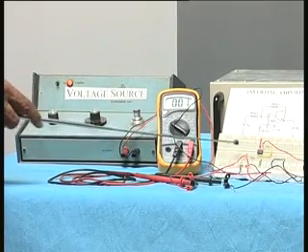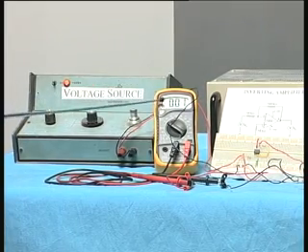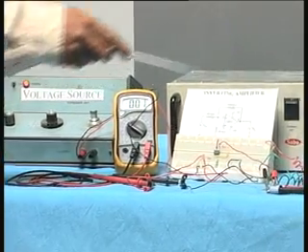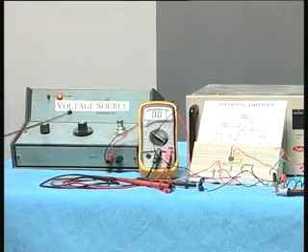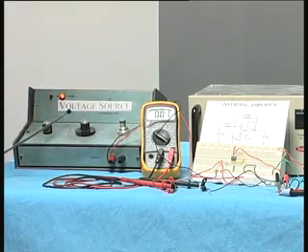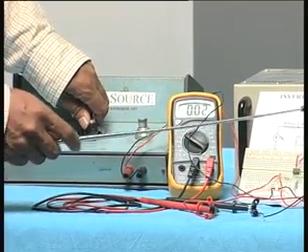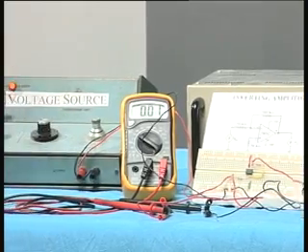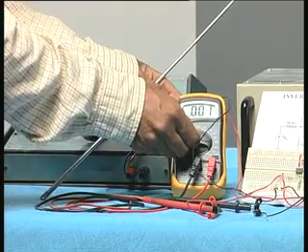This voltmeter measures in parallel. I have connected the voltmeter in parallel to that voltage source, so that whenever I change the voltage I will know what voltage I am applying at the input. At the output I have connected this voltmeter, which is again a multimeter in the voltage range. Now I have got here 100 millivolts. So the gain is 100k divided by 10k, that means 10 times. It is actually 10 millivolt. I will come to a lower range, then it will be better.